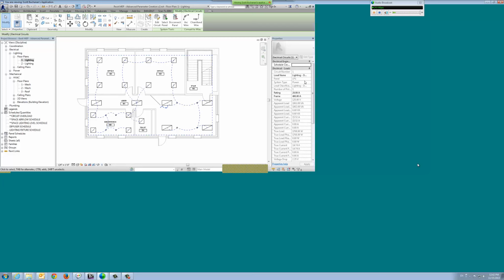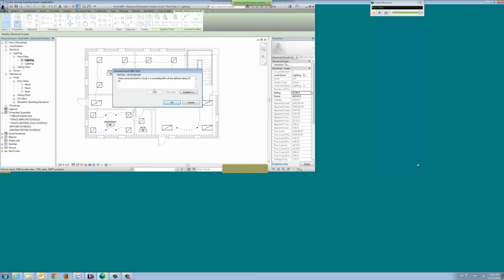I'm looking at the circuit properties. See, we're at 20 amp, which is default. Again, I can't touch that either. Going down through here, let's see a 15 amp flag that is overrated. Nope, we're still safe for the 15 amp. So back at 20, not overloaded. Nope, there we go. Once we click back in with that 15 amp, we were overloading. So there's one notification. If someone was in the panel schedule making changes to that default 20 amp and made it 15, this is the alert they would get.